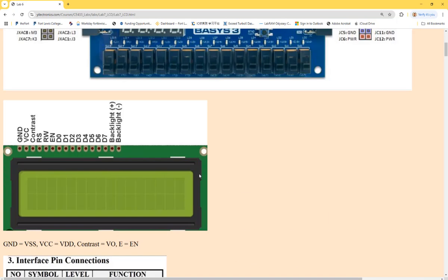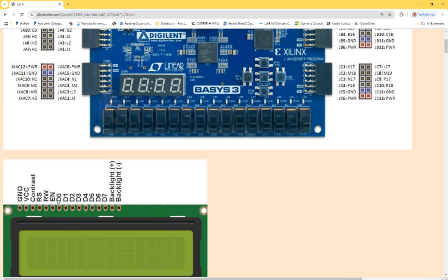If you look at this one, it is being multiplexed. Whenever you are sending data in here, you have to tell the LCD module if you are sending an instruction or data, right? And which pin is controlling that? RS. So keep in mind, this is super basic for the LCD. This will be on the final exam eventually. Okay, so RS is controlling that, right?